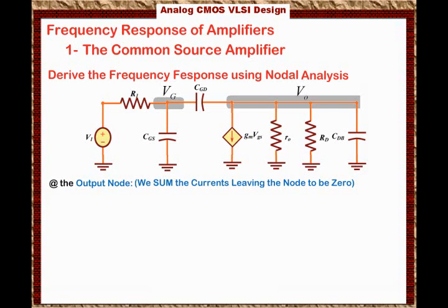And I stress this in the early circuit courses. I might deviate from most of the circuit authors, but the reason I like to sum the currents leaving is that it is systematic, and also when it comes to analyzing complex circuits it becomes very intuitive. For me it is much easier. I come to the node, I sum the currents leaving the node, and it equals 0.